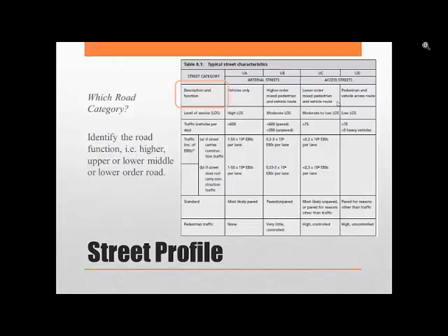Arterial streets carry a heavier load, thus their loads are justified. All attempts should be made to pave arterials carrying bus and heavy goods vehicles to a suitable, relatively low risk pavement standard. Where there are financial constraints, the street network should then be prioritized on an economic basis to identify candidate streets for upgrading, also known as a pavement management system.